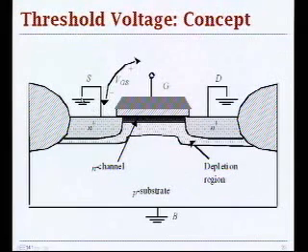When you have initial case where all your electrodes are at ground, zero potential, what you have in that case is depletion region between your PN junctions that are formed between drain and substrate and source and substrate. And your transistor is turned off.